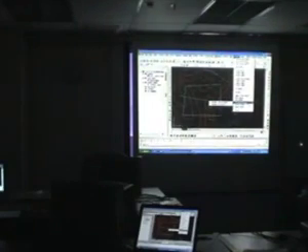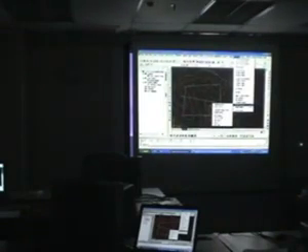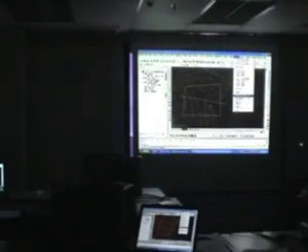The third method is the section method. The section method is another very popular manual method where they basically cut cross sections across both the existing and proposed level. They take the difference, multiply it, and total everything up together, and they get the volumes from that. So I'm going to show you all 3 methods and show you how easy it is to use.